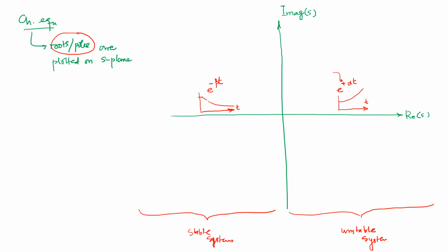Then this is the story when you have the poles exactly on the horizontal axis, but whenever you have poles with some imaginary part, like a complex conjugate, on the imaginary side, then obviously you're going to have something like this arrangement, and that would mean that you have some sort of oscillations in the system.